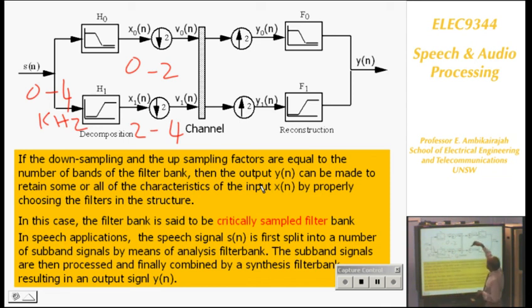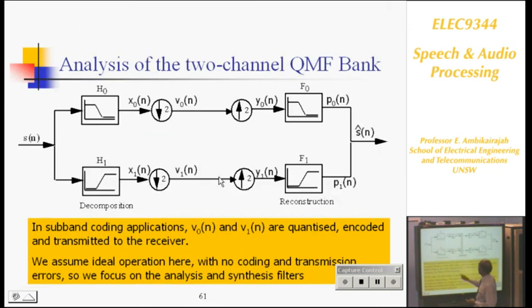And then I can downsample and upsample. Downsample is to reduce the number of samples from here to here. That causes aliasing. But then you upsample and add them up here. You need to add them up here. This adding sign, you see? When you add them, they'll cancel out. The aliasing will cancel out.